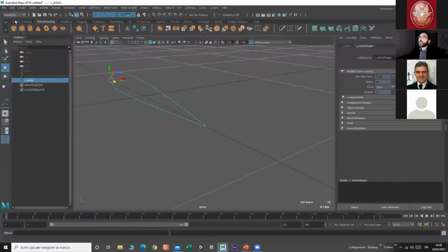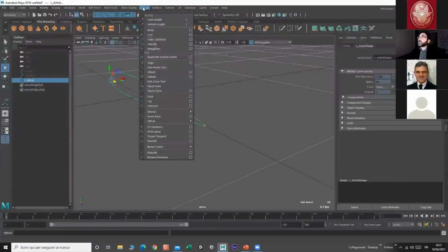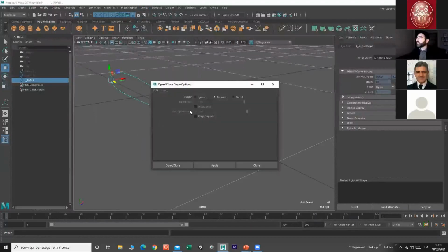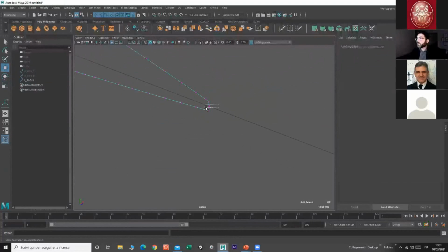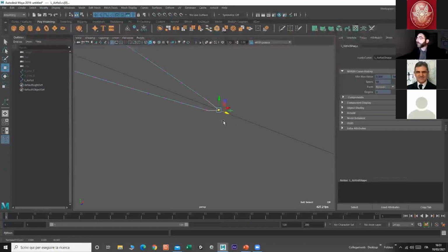Go on modeling interface, and then select the Curves tab and close your real line, but you need to check the box. If you select the name, the program applies the default setting, but you can change the setting by checking the box. In this case, I use the default setting. Now we can again select the vertex and they are connected. Okay, this is a very important thing.